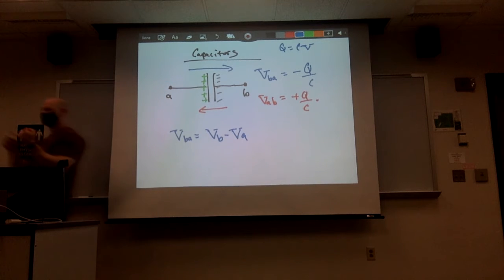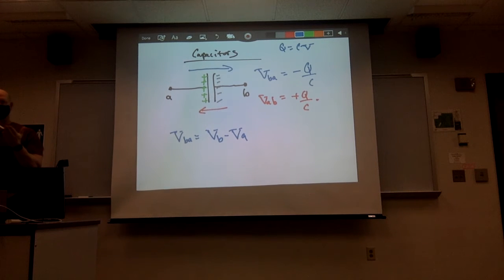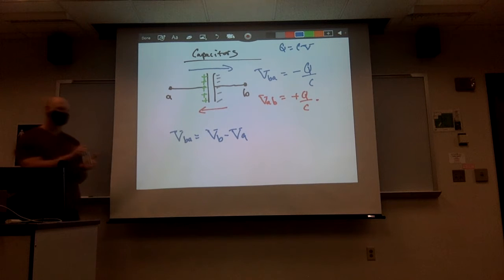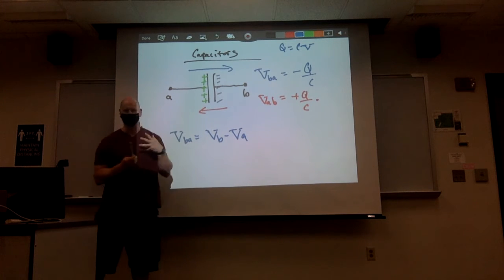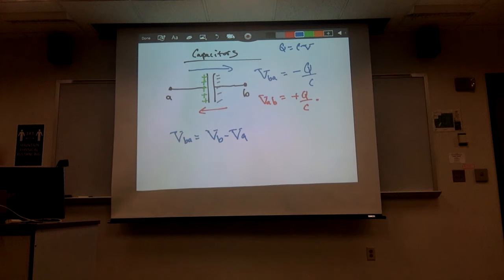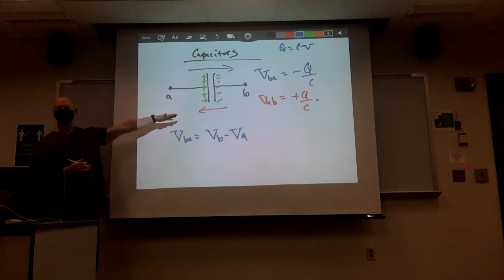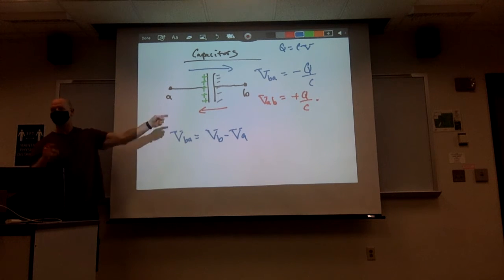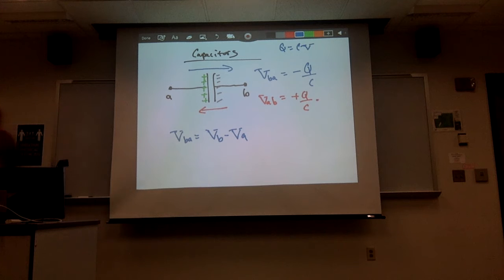Okay. So Kirchhoff's loop rules and the way we analyze these particular circuits comes down to, again, just the loop rule, saying anytime I go through a closed loop and I go back to the initial position in which I started going through that closed loop, my change of potential has to be equal to 0. And the junction rule, which says that at any junction, the amount of current which comes in has to be equal to the amount of current going out, plus these 3 different sign conventions. These things together allows us now to analyze any particular circuit that we actually want to take a look at.